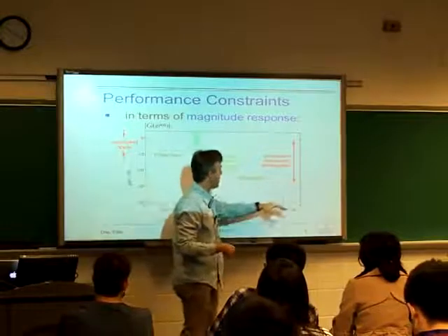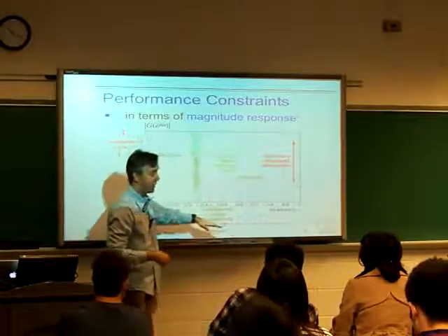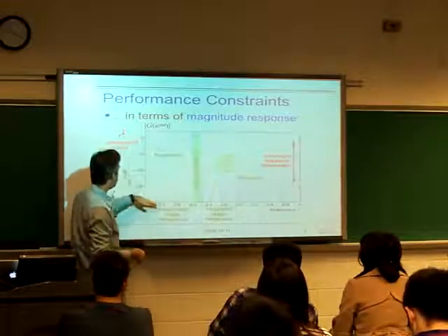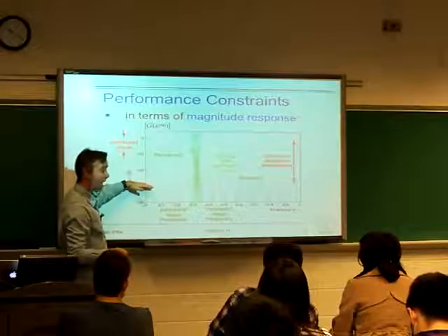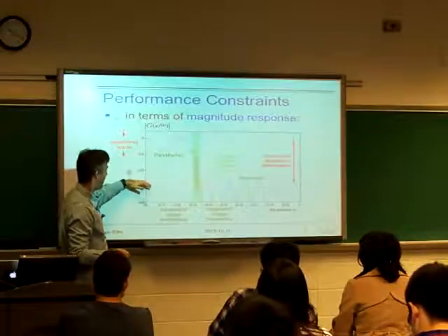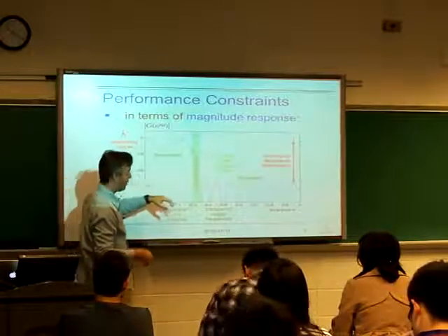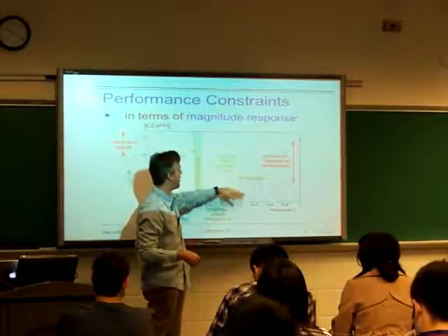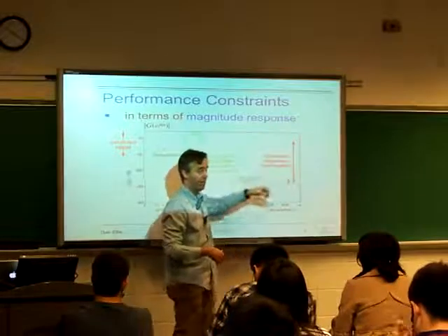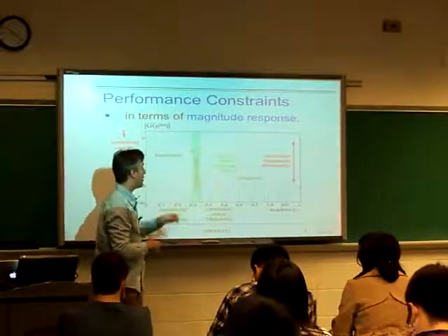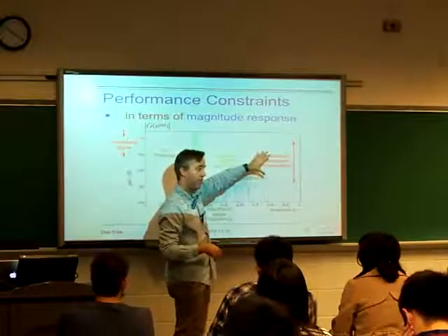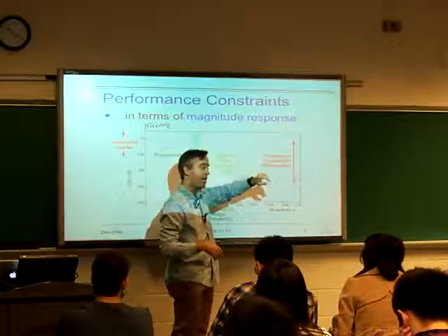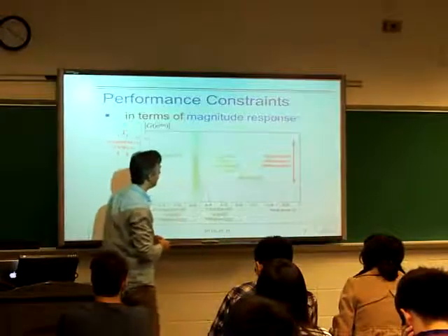Similarly, in the stop band, we say, well, we'd like the gain to be negative infinity dB, like it to be 0, but if it goes a little bit higher, maybe we'll have some largest gain that we'll tolerate. So maybe, in this case, minus 28 dB, which is not that small, but there's some value here. As long as the gain is always below this minimum stop band attenuation, then okay, that's fine, we'll take that filter. And of course, we can make these larger if we're worried about this, but we're saying we're not insisting that it be infinity. It can be some finite value.